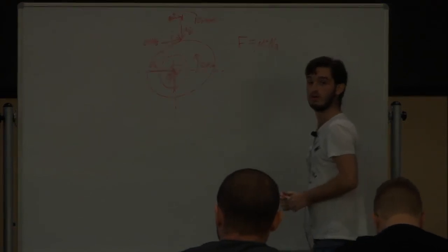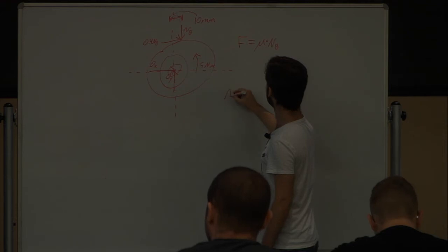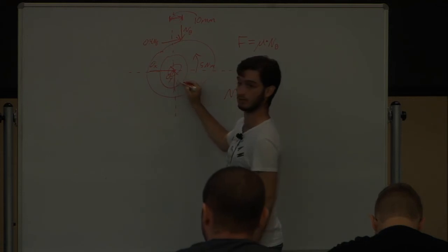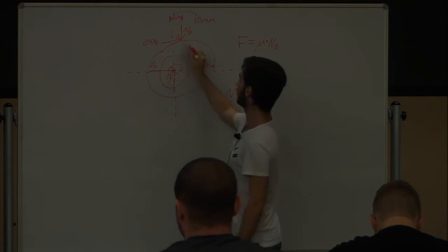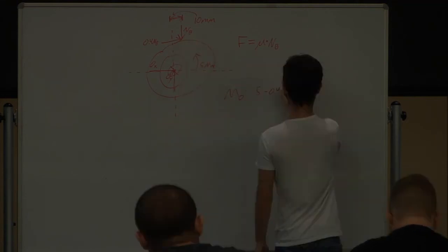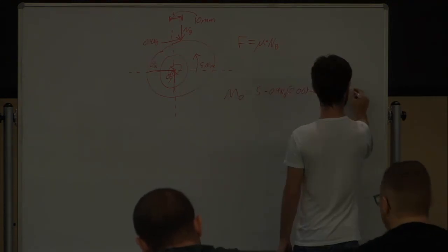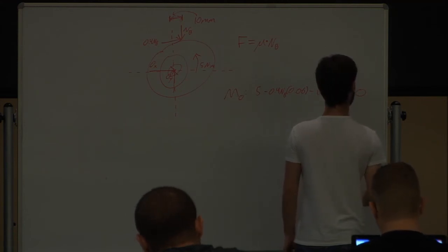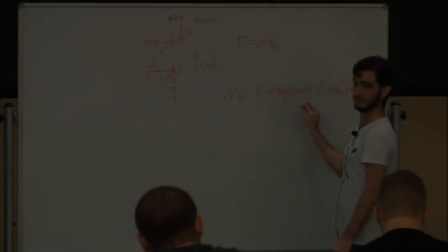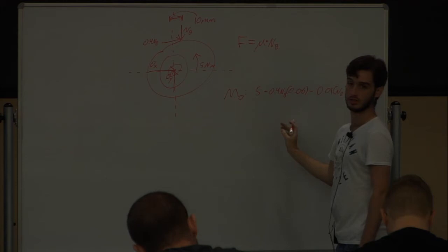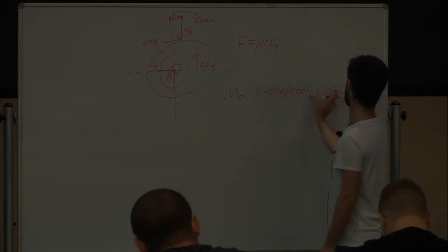Because if we do a moment about O, these two cancel out. These two forces are creating a moment about O, and that applied moment. So we can easily solve for NB right here, just doing the multiplication out, combining these terms and taking the 5 over. So our NB equals 147.06 newtons.